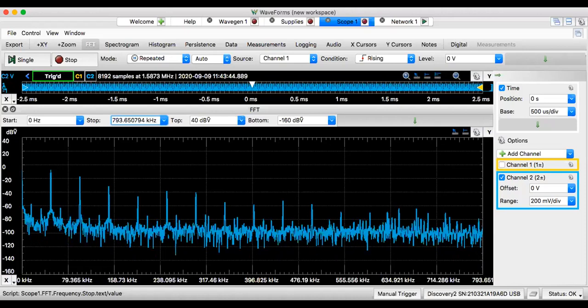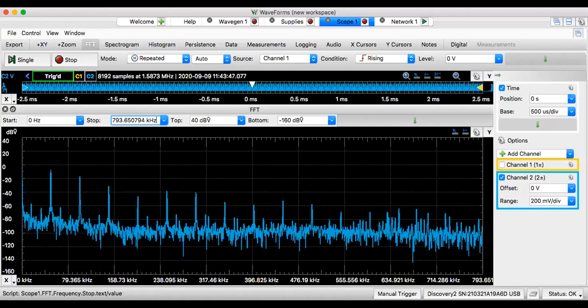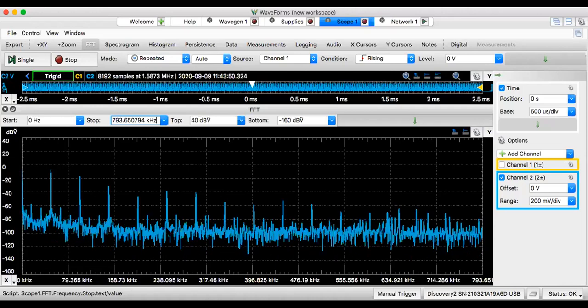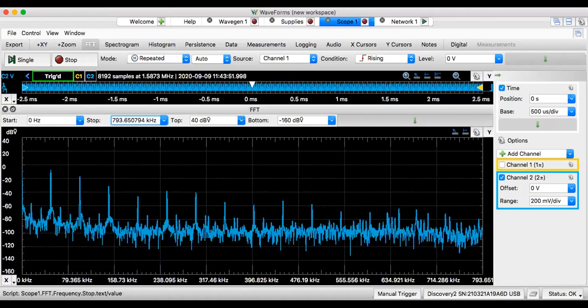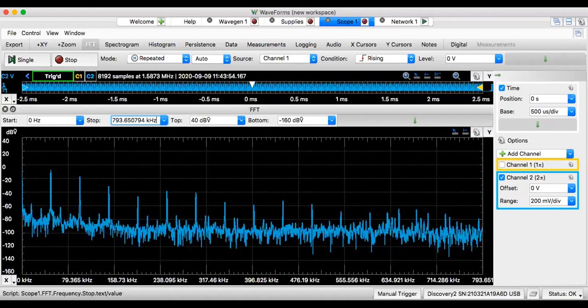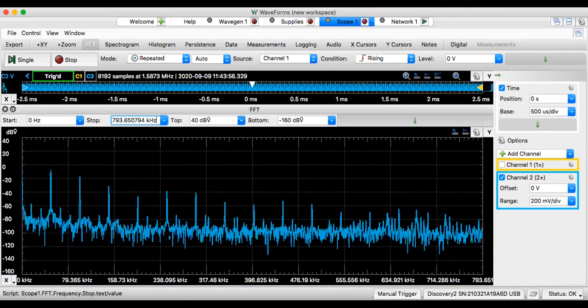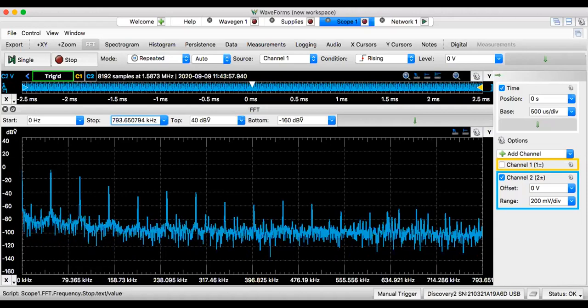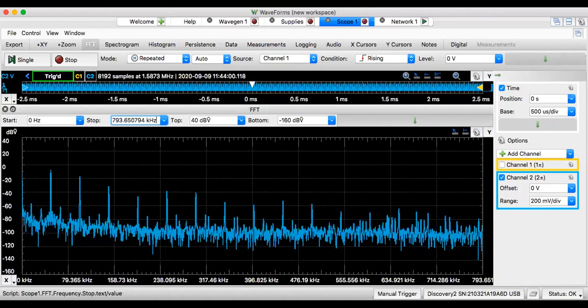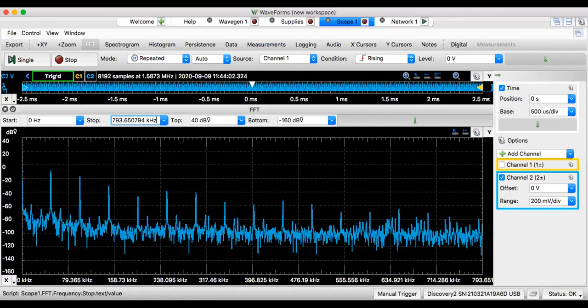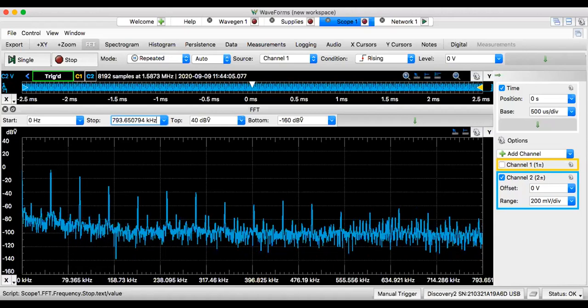Distortion is measured by total harmonic distortion, which measures the harmonic distortions. The definition of total harmonic distortion is that all those energies add up, divided by the base energy.